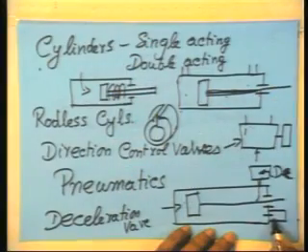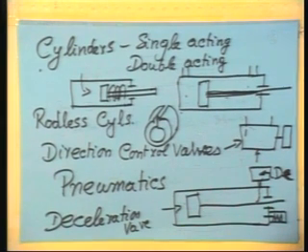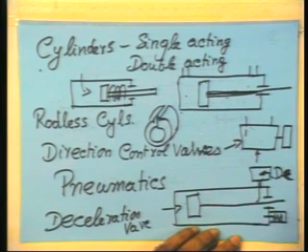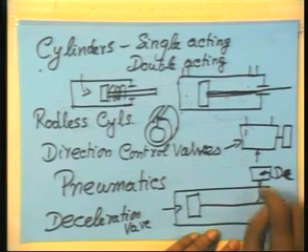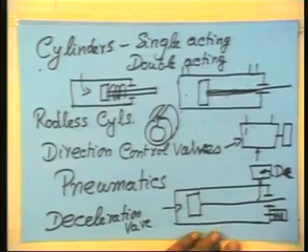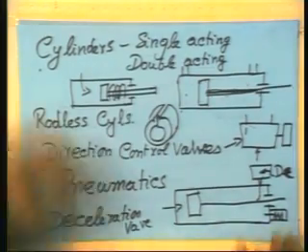Sometimes there are external shock absorbers fitted here, spring and dashpot. Sometimes they are also used. You may use a deceleration valve plus this, or no. Pneumatics is quite fast, it simply goes. But high speed also means that it will suddenly go and bang, so you have to have these devices towards the end of the stroke to control it.